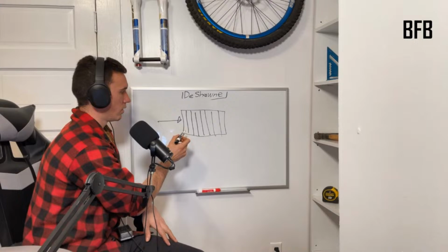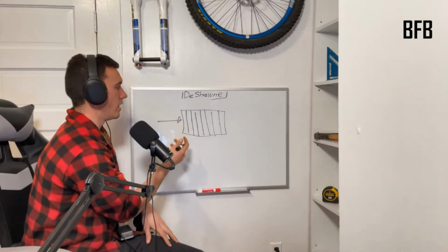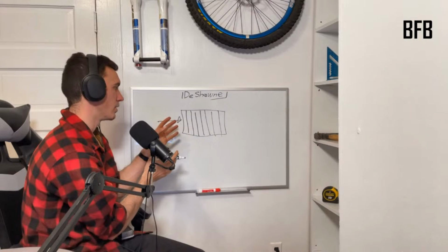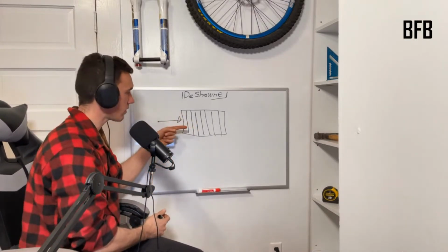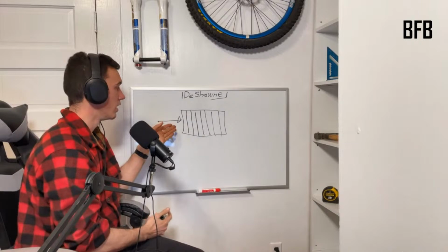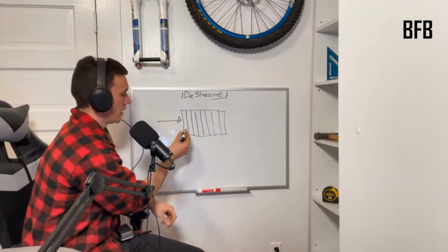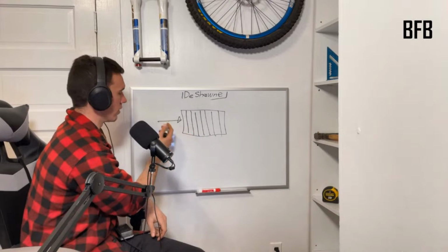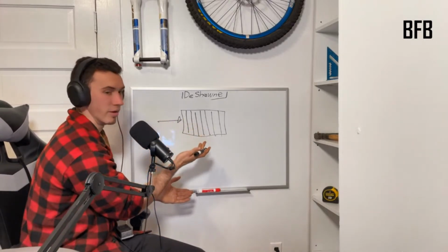So what's going to happen is each one of these ceiling joists, when they're installed, they're turned in such a way that they'll bend very easily in this direction. And so one thing you could do to try to stiffen this all up is you could add blocks. If a force was exerted on this first one, what would you do to help it out?